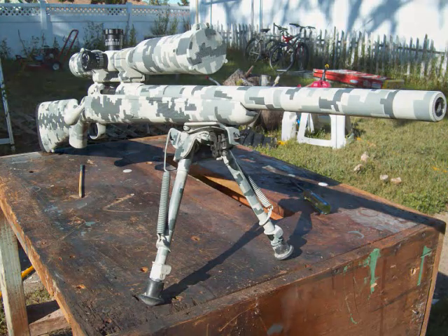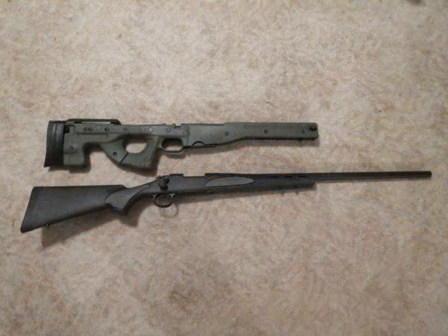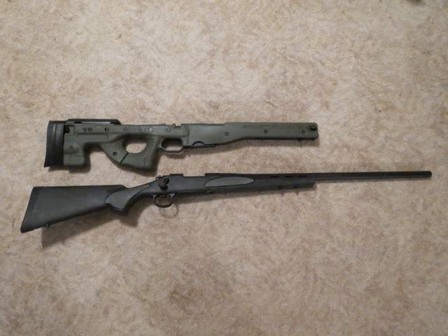You know what I mean? And if your plastic stock gets really cold, in cold weather, it can get a lot harder and stiffen up a little bit. That will totally change how your rifle barrel vibrates, especially if you have any kind of tension or contact points on your injection molded stock. So if you've got one of those, in my opinion those are actually worse than wood as far as the harmonic problems that arise. So if you've got an injection molded stock, you definitely want to make sure it's free floated.